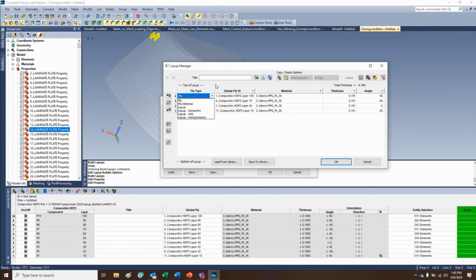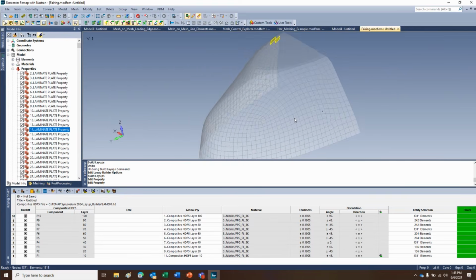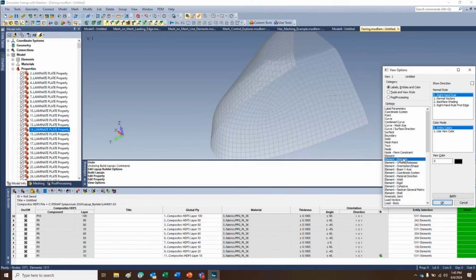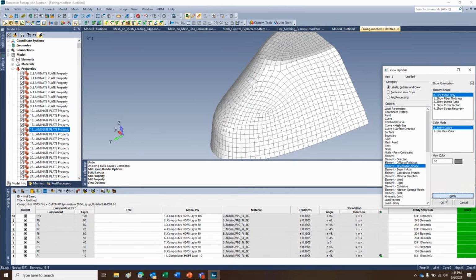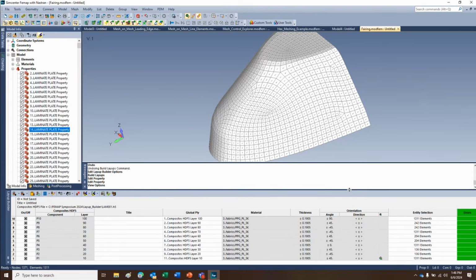And that angle is relative to what coordinate system? That's the material. FiberSim actually gives us, for every element, what the base is. That's coming from FiberSim. Okay. Yes. And in Femap, you turn on the material angle, we'll see what it told us to do. That data came in from FiberSim as well. So it's relative to that. Okay. All right. So again, it's really neat functionality.